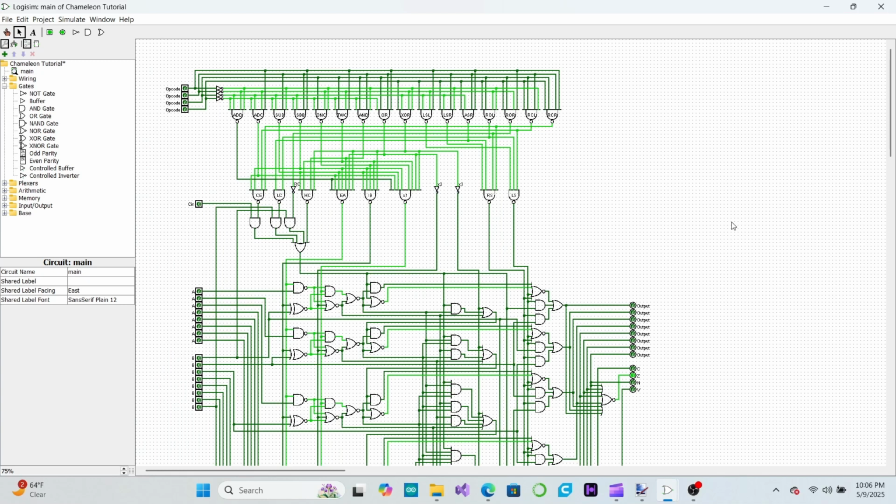Before we add this circuit to our CPU, let's make some minor modifications to our ALU. It is often beneficial to have the ALU simply pass along one of the inputs unmodified to the output. To do this, we will add another input to the ALU. We'll call this input op because when this input is off, it will simply load the B input to the output, bypassing any operations that we would have done normally. We'll wire this signal to each of the decoder's inputs. This disables the decoder when we want to do a load operation. We'll also connect this signal to any of the NAND gates associated with the control signal we want to send to the ALU when doing a load operation.